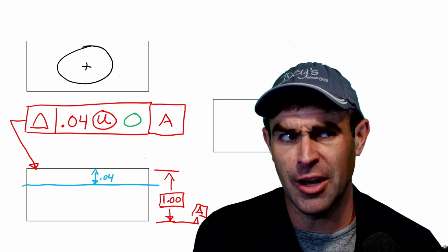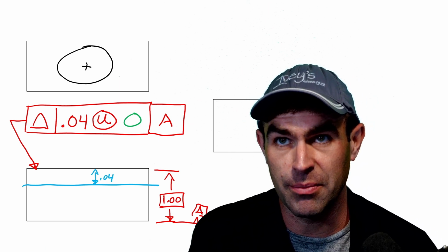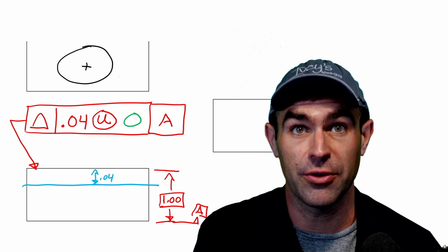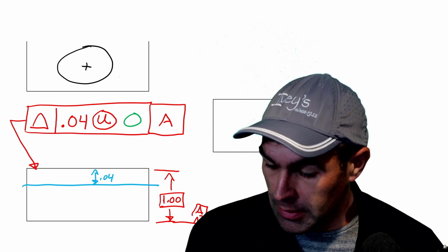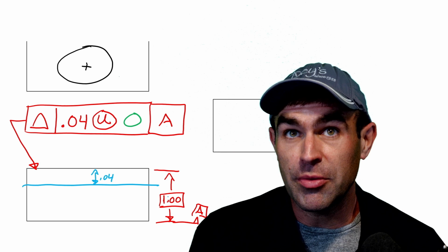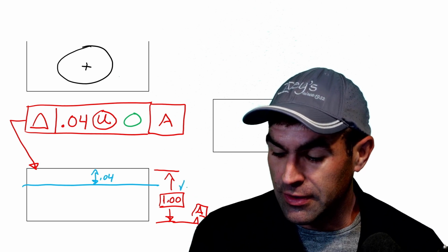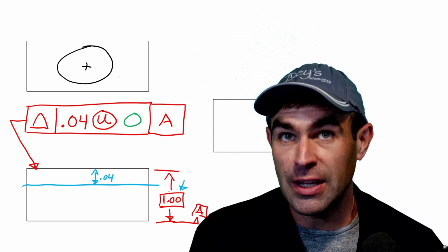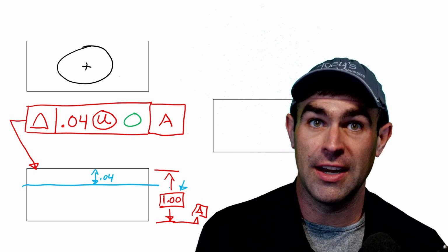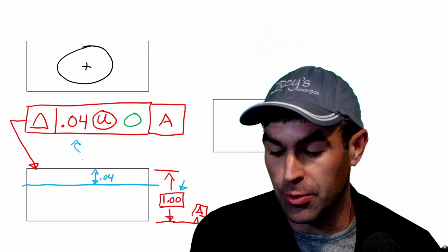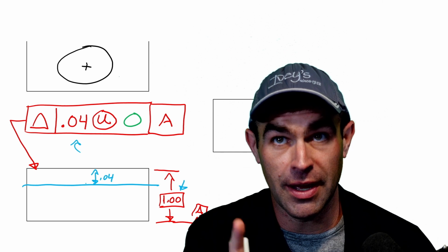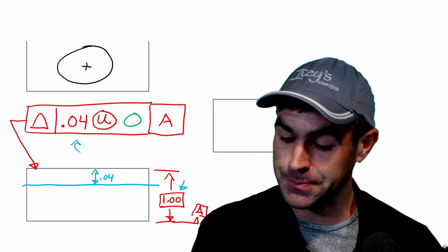And I mentioned upper and lower limits. Somebody emailed me a question, so hopefully this answers it for you. Our MMC is equal to the basic dimension here, and our LMC is equal to the basic dimension minus the entire value of the profile, because it only applies on one side.